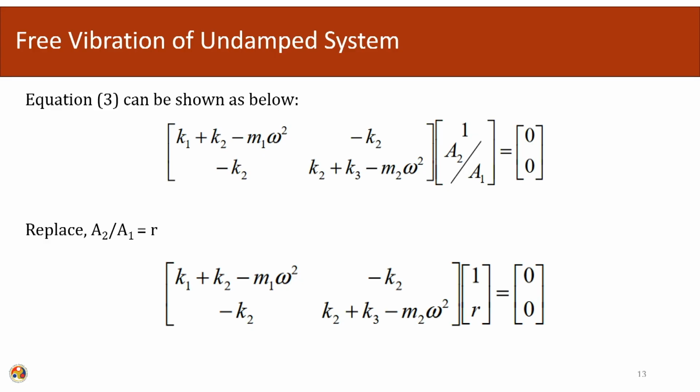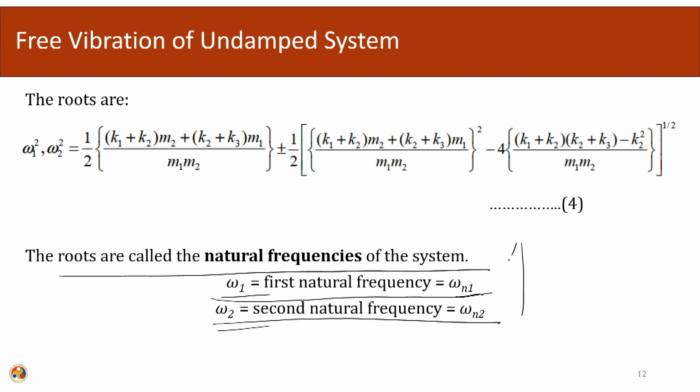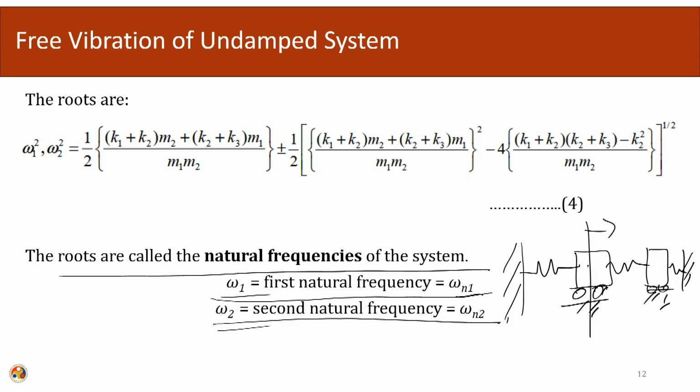So, picking up from the last time, we had reached where we were able to calculate the frequency of the system. So, we calculated the natural frequency of the system. omega 1 was the first natural frequency of the system and omega 2 was the second natural frequency of the system. What it means is that we were dealing with this system, having 2 degrees of freedom, mass m1 and mass m2, and the degrees of freedom x1 and x2 were there.